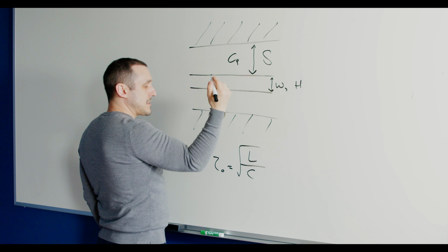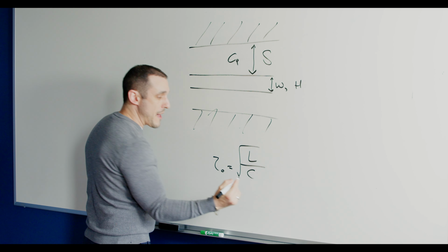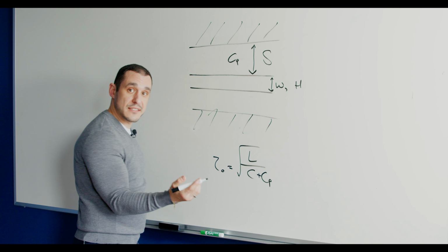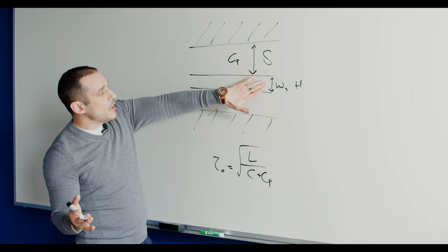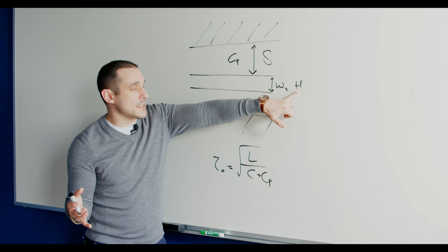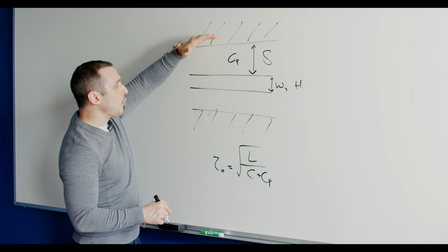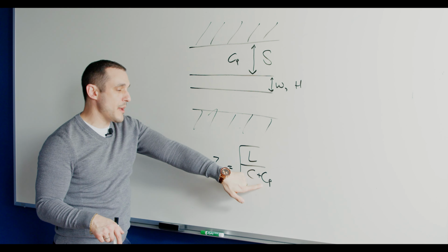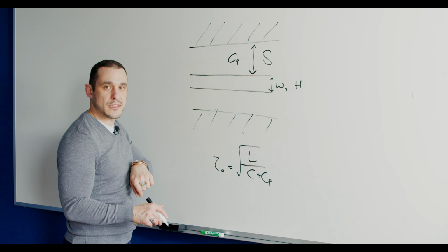Now, this capacitance is modeled as being in parallel with the trace's self-capacitance. And so we're basically adding in some CP down here. So this is very simple. If all we did was keep the width constant and the thickness of the dielectric constant, and then we start to bring in this grounded copper pour, we're now adding in this parasitic capacitance. And so since we made this denominator larger, we now just reduced the characteristic impedance of this line.